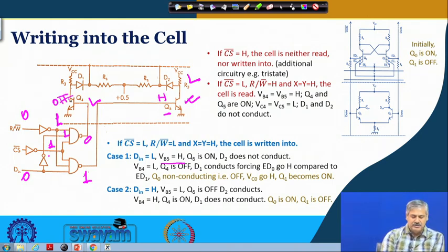Okay. So this voltage over here is high. Now this diode conducts. High means close to VCC, close to 5 volt, depending on how much IC/RC drop will be there, right? And there is a 0.7 volt drop over here. So now this voltage is much larger than what we had seen before. Okay.